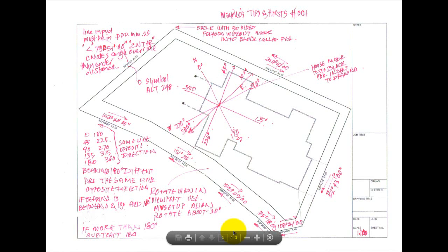You can put any one in that you like, put a base point in there, and then rotate it about minus 30 degrees, and you'll find then that if you go into the viewport and move things around, there's a bit of a pan function there in the viewport, so you can just move it so it fits in nicely like that, and then lock the viewport, set your scale at round about 1 to 10 to 1. That's what I set it at, which is actually 1 to 100, I think.